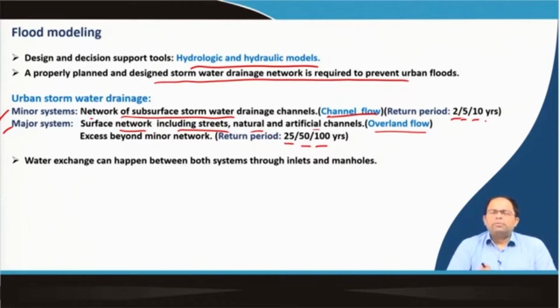So, this excess water we can assume will come out through the manholes or at these particular nodes, and that will create flood in that particular area. That means the water is first getting into the sewer system. Even when we estimate the maximum amount of water based on the time of concentration for that particular catchment coming to the sewer network, because it is not able to cater to that, the excess water comes out via the nodes. Maybe physically it is not exactly like that, but when we do flood modeling, we think in that way.